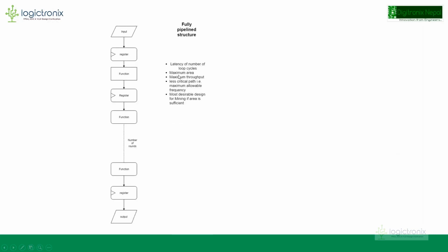So now this is the design that today I'm gonna discuss in detail. This is the best, favorite design for mining applications in most algorithms. So we've got input over here, and we have a register, and we have a function, and we have a register again, function again, register again, function again, and we go on until we repeat this register-function block that many times. Like for Keccak, we repeat this register and function 24 times. So there is a new function for every iteration.